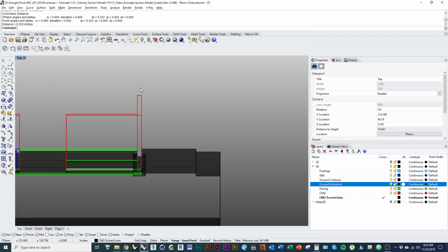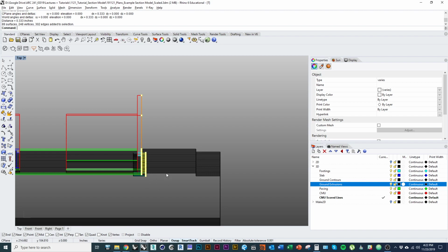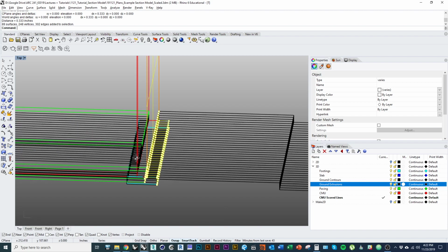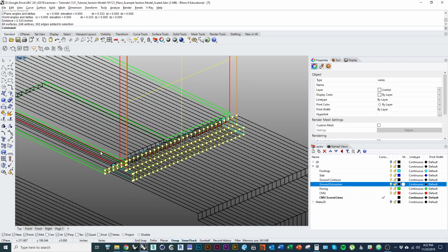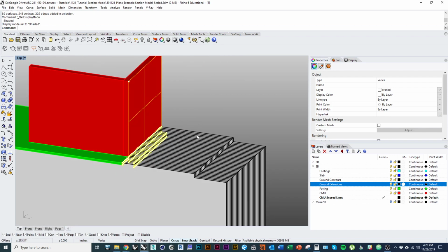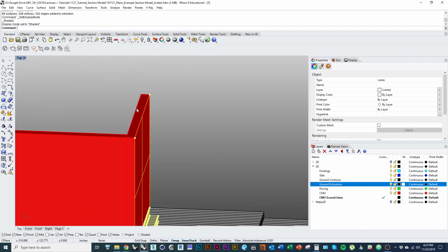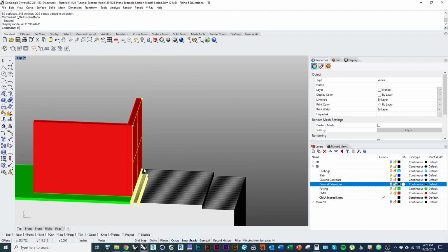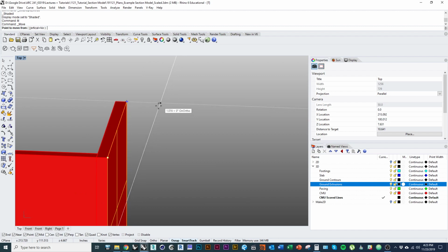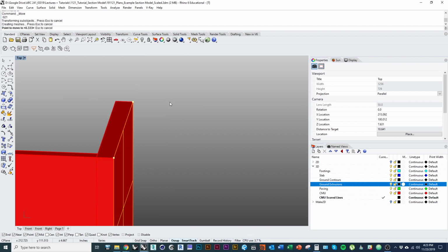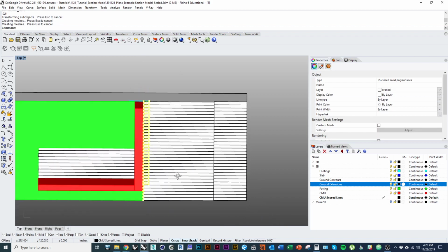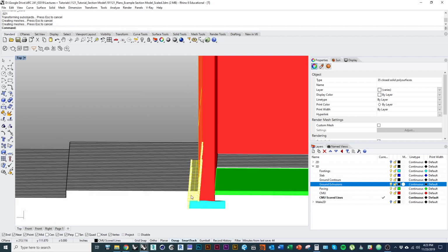So I'm going to hold Control-Shift on the keyboard when I'm in this view, so this angle, and click and drag to the right around all the edges that meet that face. So I'm selecting the edge of my paved layer here, all the edges of my contoured ground plane, as well as the footer and the wall itself. So I select a whole bunch of the edges of this geometry. Now I'm going to use the command move. Quite simple. Type in 0.021 and move it over by 0.021. So now I've adjusted all of my geometry by that amount.